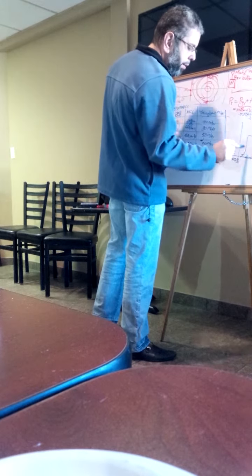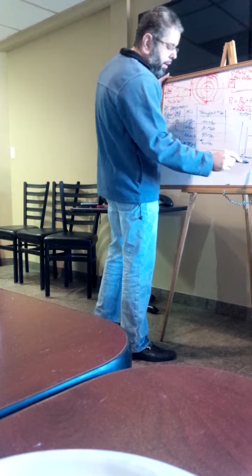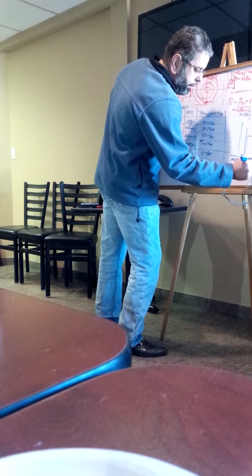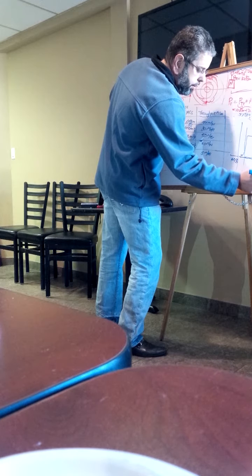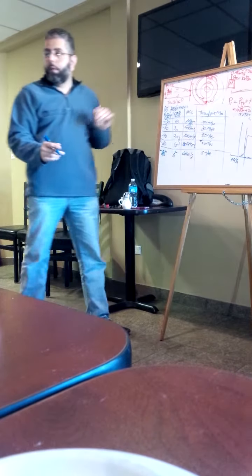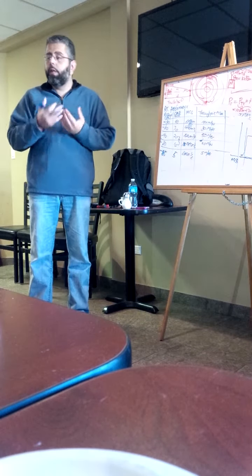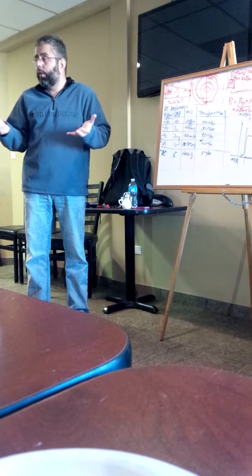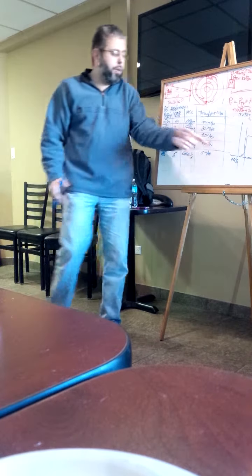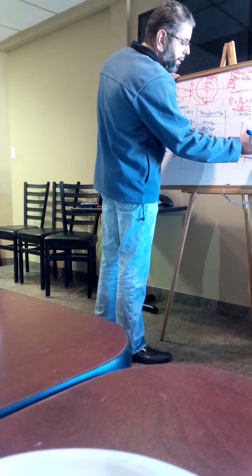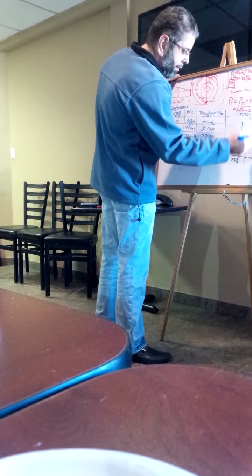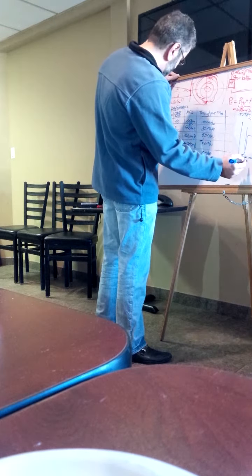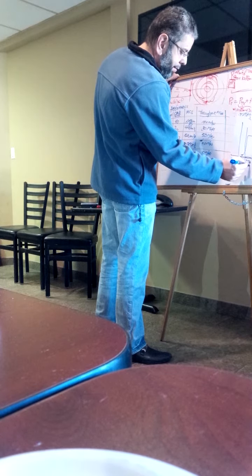This is just the noise floor. This has nothing to do with interference just yet. Your noise floor is what your receiver generates as noise just by having resistors and active devices on the board. He's down here, and if I'm getting a signal at minus 50 dBm, let's just give an example. Let's say the noise floor is at minus 95 dBm for now.